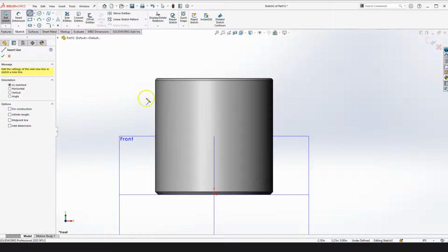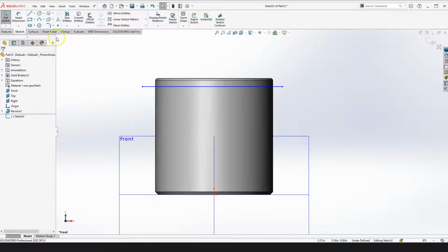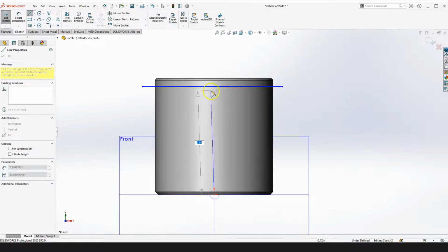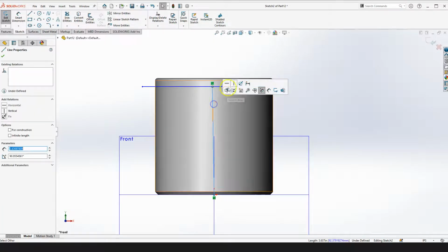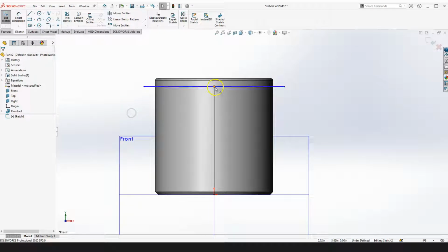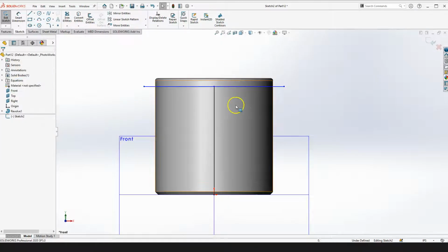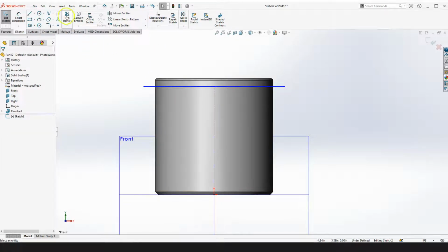So just make it a line. Just make sure your line just crosses the body there. You can define it a little more. Click on the center point and just make it like a midpoint. Make this guy vertical and click on that point and that line and just its midpoint there and make that a construction line there and just give it a dimension here.